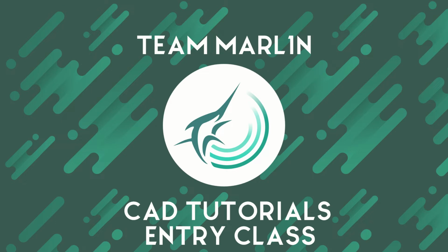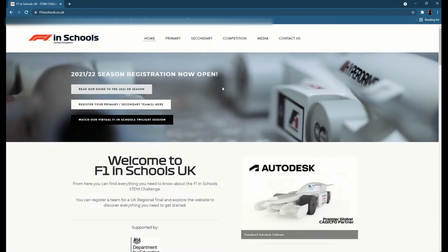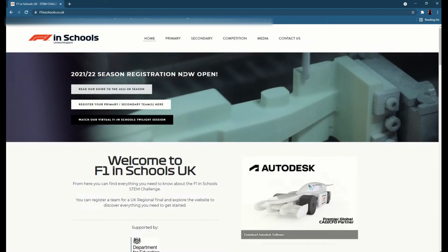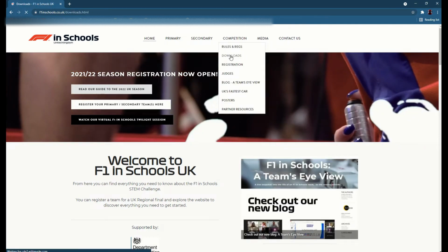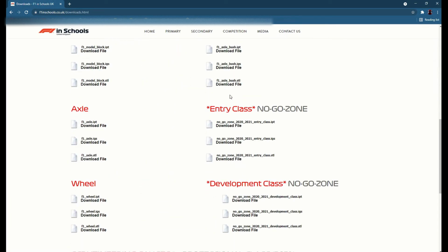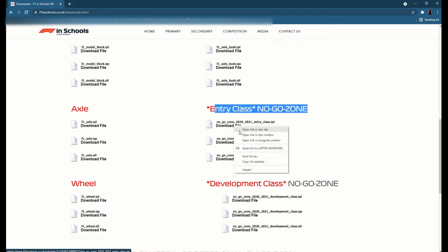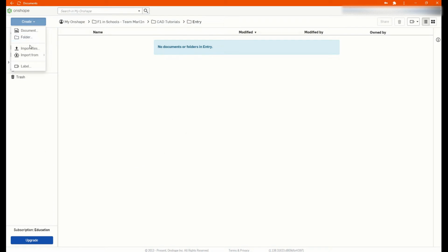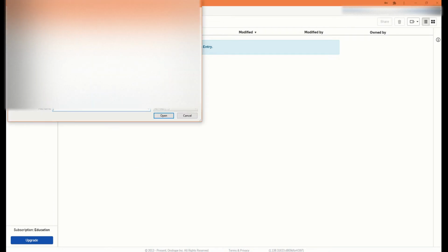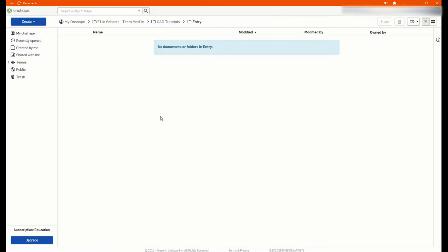In this video, I'm going to take you through the basics of OnShape and how to import the no-go zone into a document. So firstly, you want to go to the F1 Schools UK website and then go to the competition and downloads area. Then scroll down to the entry class no-go zone and download the IPT file by right-clicking and then save link as. Once you've done that, go to OnShape and then create import files and select the IPT file.